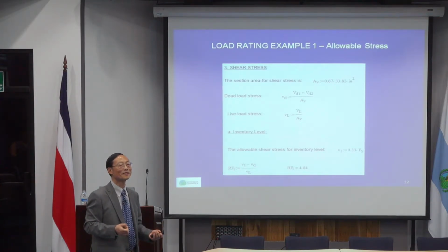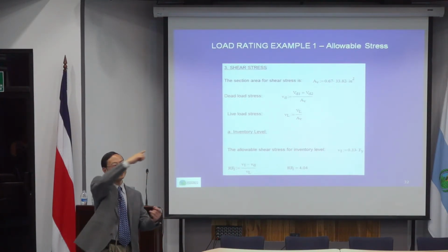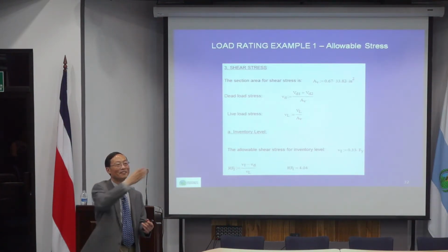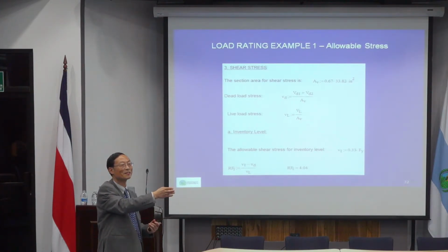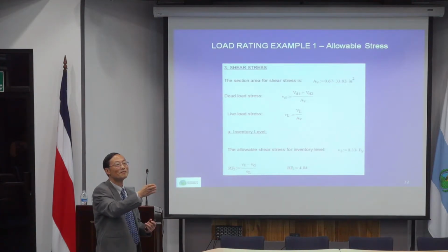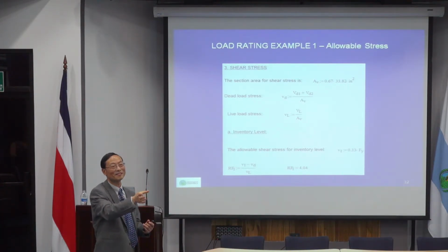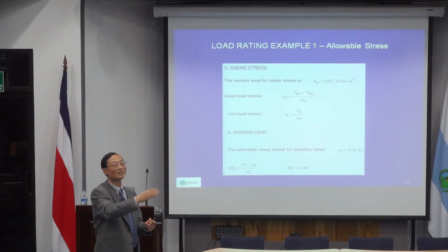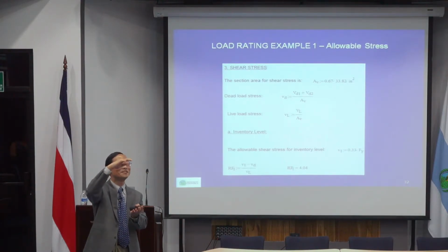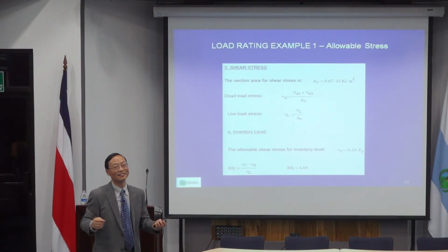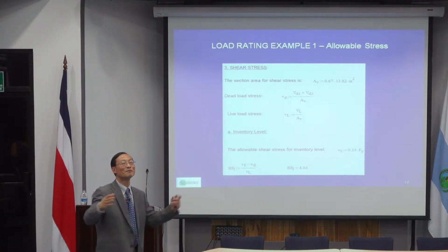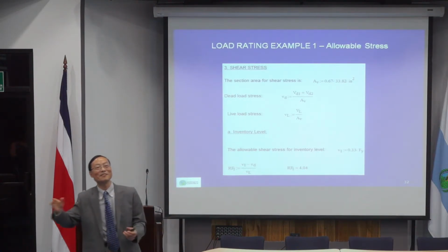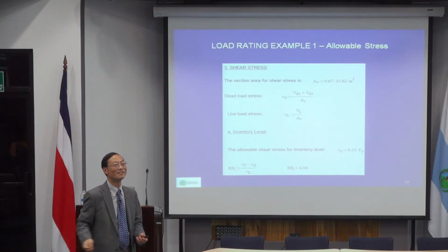For example, for post-tension, if you have a post-tension cable of that shape, you may select the middle span. Sometimes the middle span may not be critical. You may select something like 0.7, 0.8, that area, because your d is much smaller. So that's why, even for the same member, they may calculate different sections, just to make sure everywhere is fine.